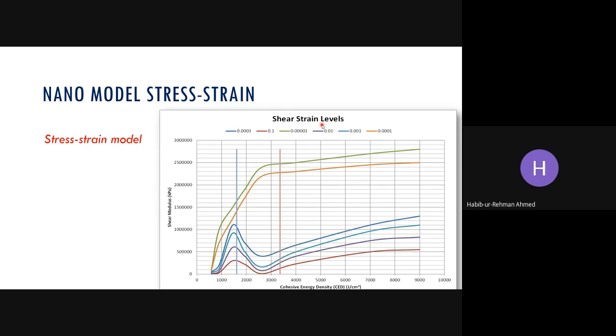I will say swelling soils because whenever clay is present in some substantial quantities, even sometimes 20, 30, 40%, even sometimes 10%, it can control the behavior of the soil absolutely, because they are just covering the sand particles because of the very high surface area. So the behavior is exclusively controlled. Even the shear behavior or stress strain behavior or volume change behavior is exclusively controlled by clay, and we can use this model.